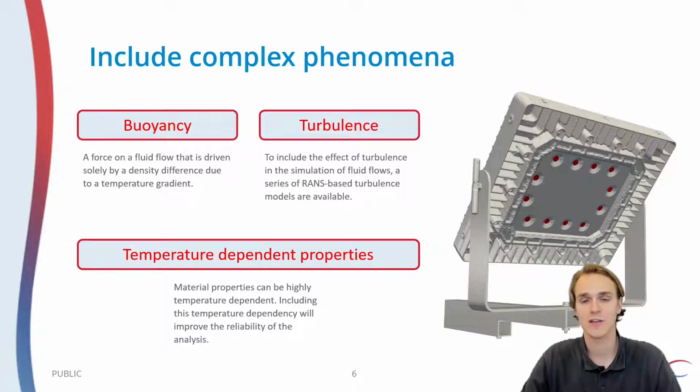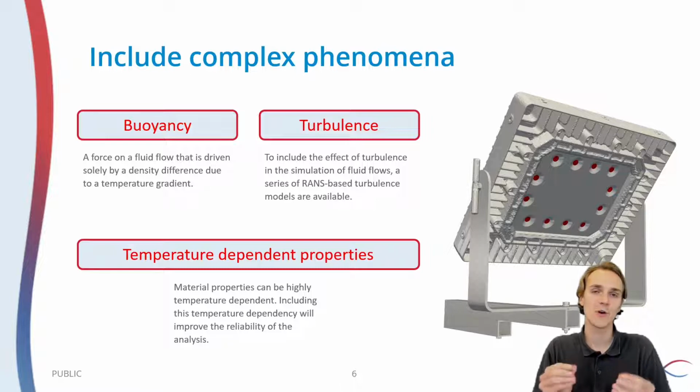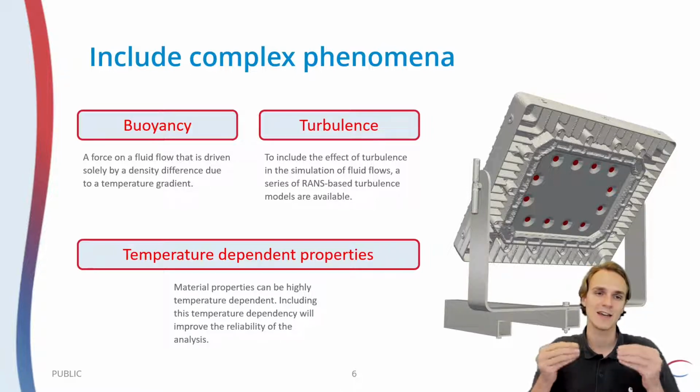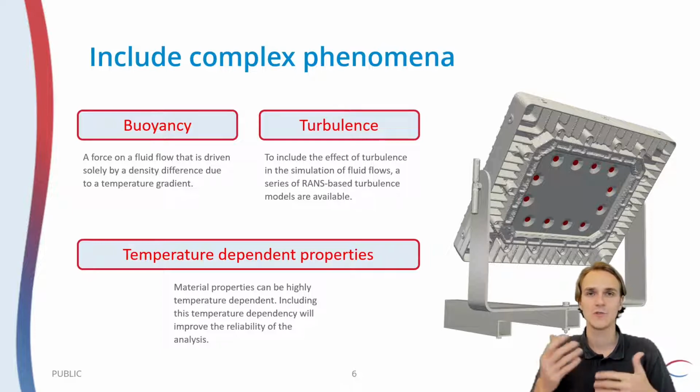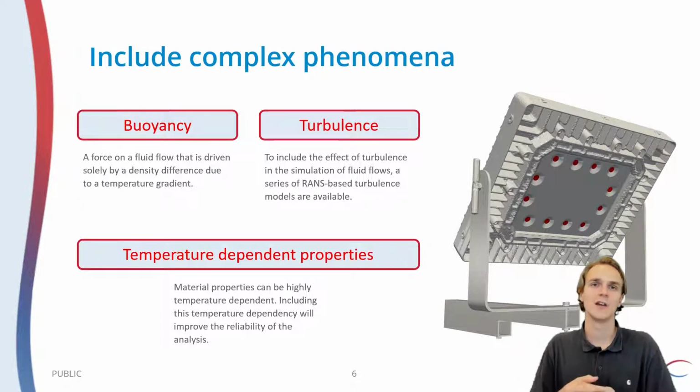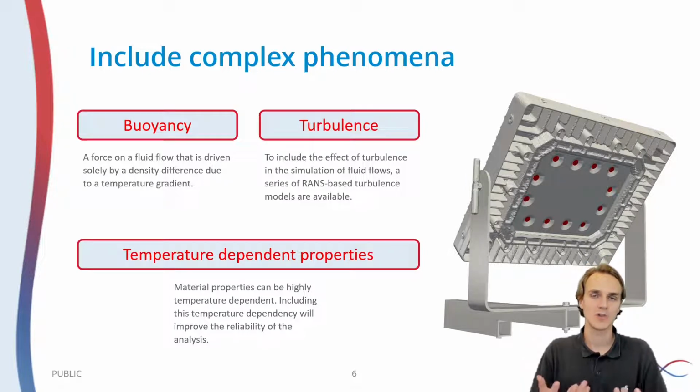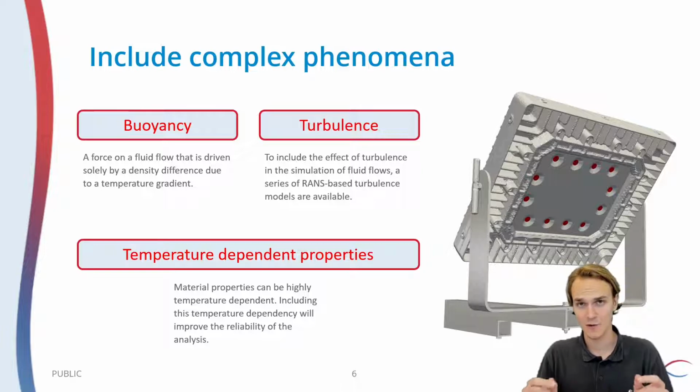Usually around a heatsink, the air particles closest to the hot heatsink heat up, and due to a difference in density, they rise, and therefore you have natural convection with some airflow around the heatsink due to the change in temperature.